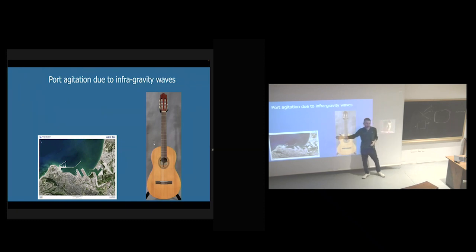Same with the harbor, just we try to plan it in the opposite way, so that it will dampen the waves. We don't want them to oscillate and resonate inside, and then you actually need to plan a harbor according to the infragravity wave regime that you have, and that's kind of a challenge, yeah? Because many times we don't have enough measurements, and we will talk about it, and we don't have a full understanding of all the generation mechanisms of these waves.